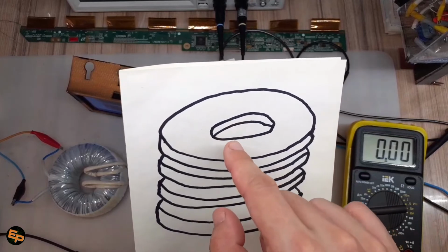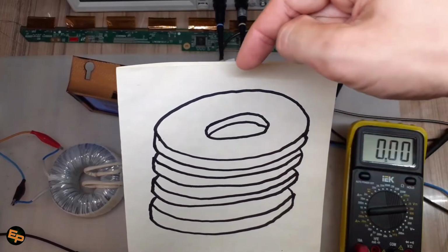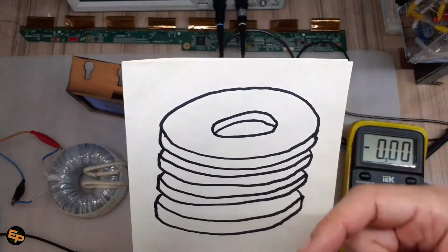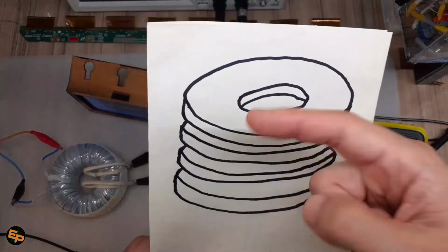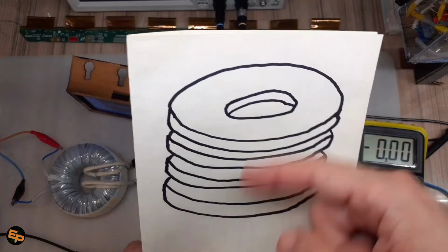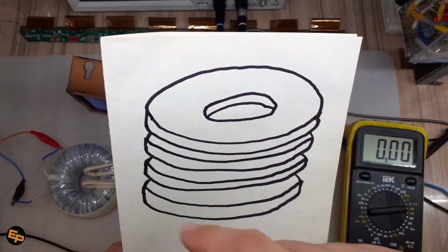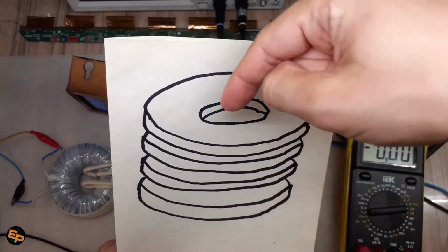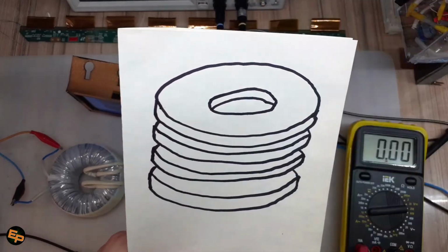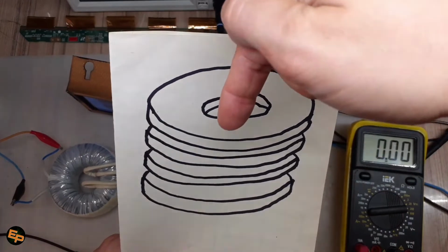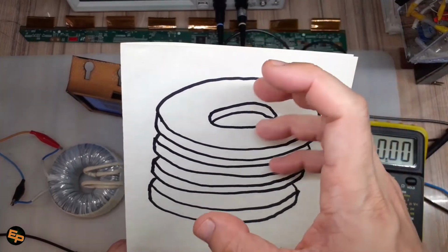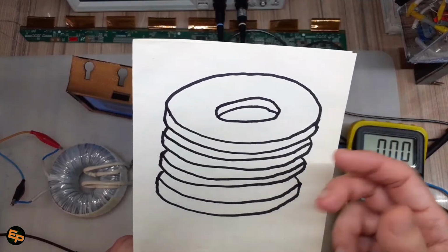The internal diameter is very important because, first of all, we will need to wind a bobbin, a coil, right, along this toroidal transformer. And second, because on the inside of the hole we will need to pass whatever wire is carrying the current that we want to measure, right?